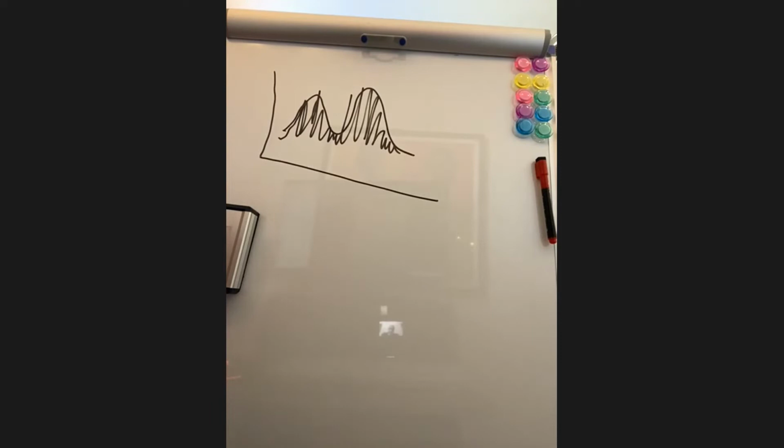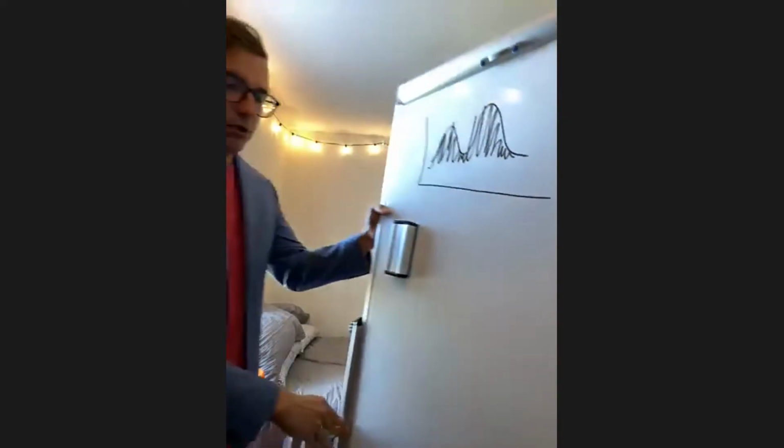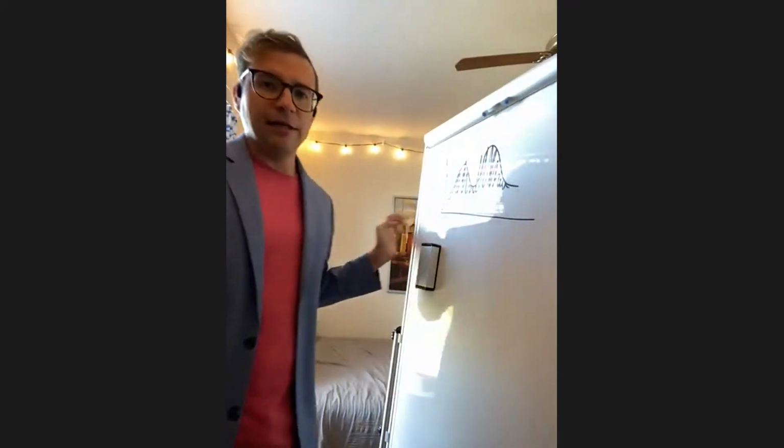So once you start, like on an intermittently cloudy day, seeing this sort of violent ramp up and down of resources, that power plant just cannot keep up. And as a result, you have frequency problems, you have voltage problems, you have situations where voltage essentially collapses on the island, or frequency collapses.